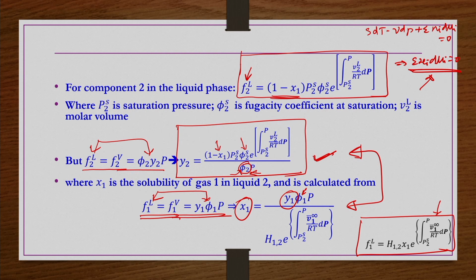It may be stated simply van der Waals equation of state is applicable or Virial equation of state is applicable. Then again we have to use appropriate Phi1, Phi2 as per the equation of state, and we know these Phi1, Phi2 are also function of composition Y1, Y2. So, again interconnection is there. Because of these so many interconnections you cannot solve these two values explicitly. X1 and Y2 we wanted to find out.